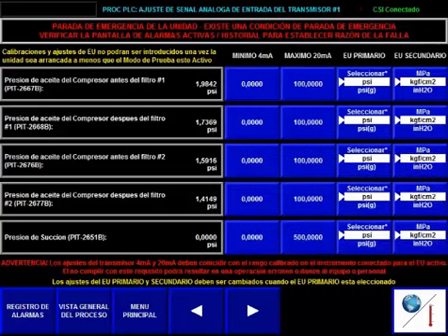You can see the low trip settings for the scrubbers are at -1. These have to be set at a negative number in order to start the unit. Once the unit is started and you've achieved a level within the scrubber, you can raise your set point so that you'll have a low trip.